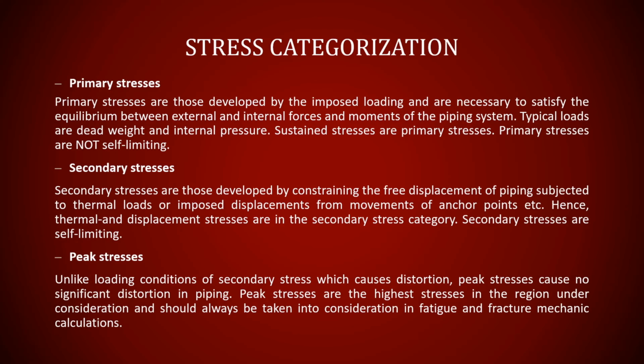The secondary stresses are those developed by constraining the free displacement of the piping subjected to thermal loads, or imposed displacement from movements of anchor points, etc. Hence, thermal and displacement stresses are in the secondary stress category. The secondary stress category is self-limiting.